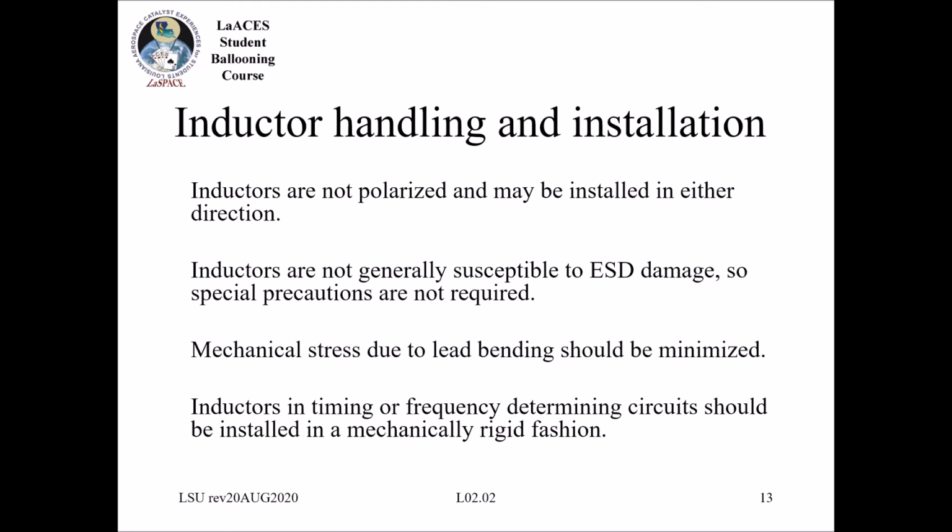They're not susceptible to ESD, but the same mechanical stresses can occur here, and inductors in timing or frequency determining circuits should be installed in a mechanically rigid fashion. So just think about that.